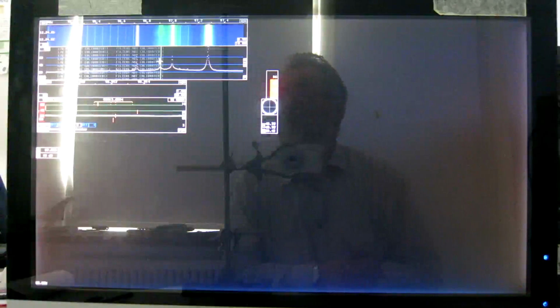And now we are up at 85%. So there is a cost for a totally meaningless higher sampling rate, because in CW mode 8 kHz is perfectly adequate. We don't have any signal energy higher than that.